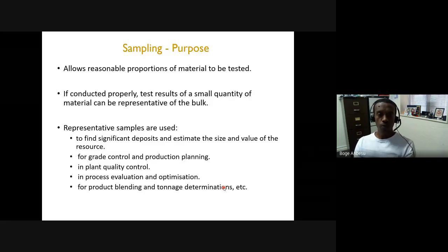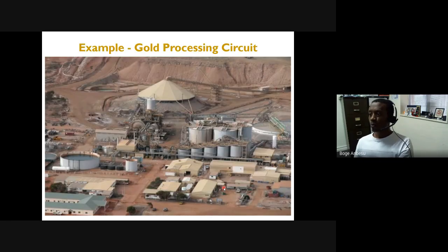So once you do your assessment, you understand the ore. Probably some of the key considerations are, whatever sample you took for your mineralogical assessment, is it representative of your sample, or is it representative of the pile? Because typically your stockpile looks like this one, okay? That is what is coming into the processing plant.